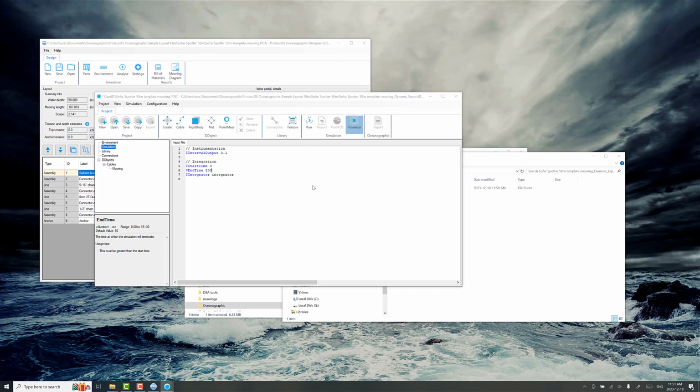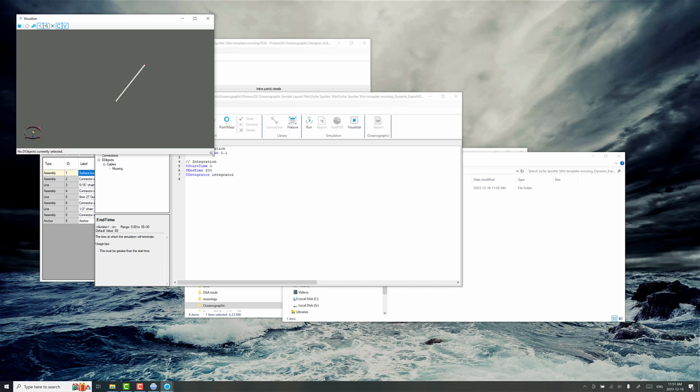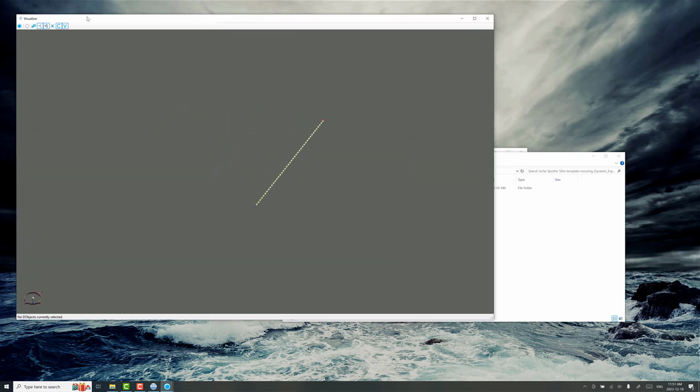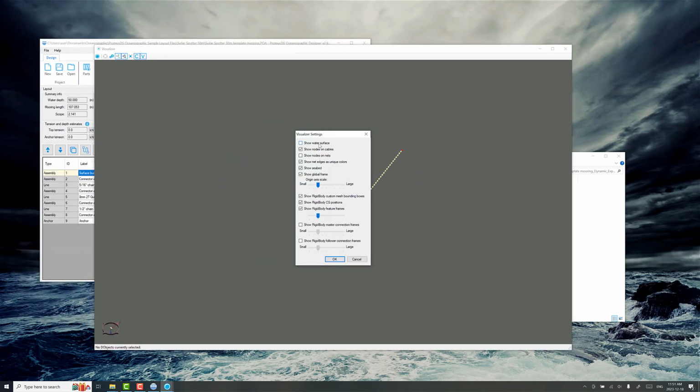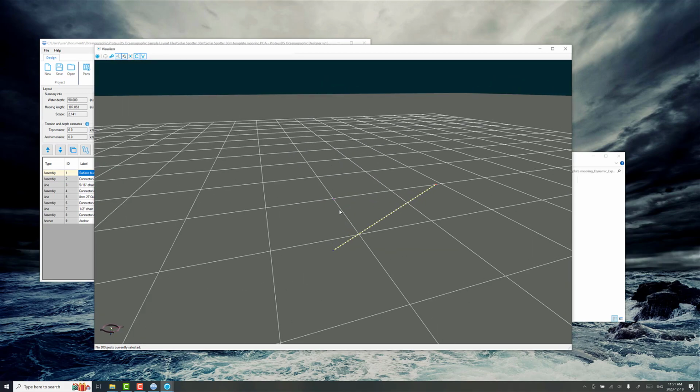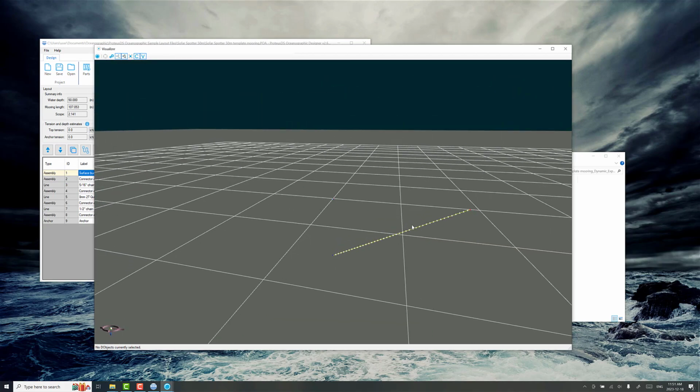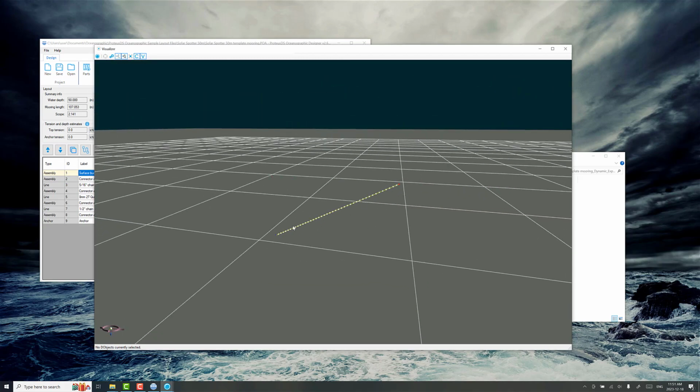And if you look at the starting condition of the mooring, what is happening here is the starting condition is just a straight diagonal line from the anchor. It's totally arbitrary, just to give it some starting state. This is what would go into the static solver and the static solution process normally, and then it would resolve a relaxed profile of this line.